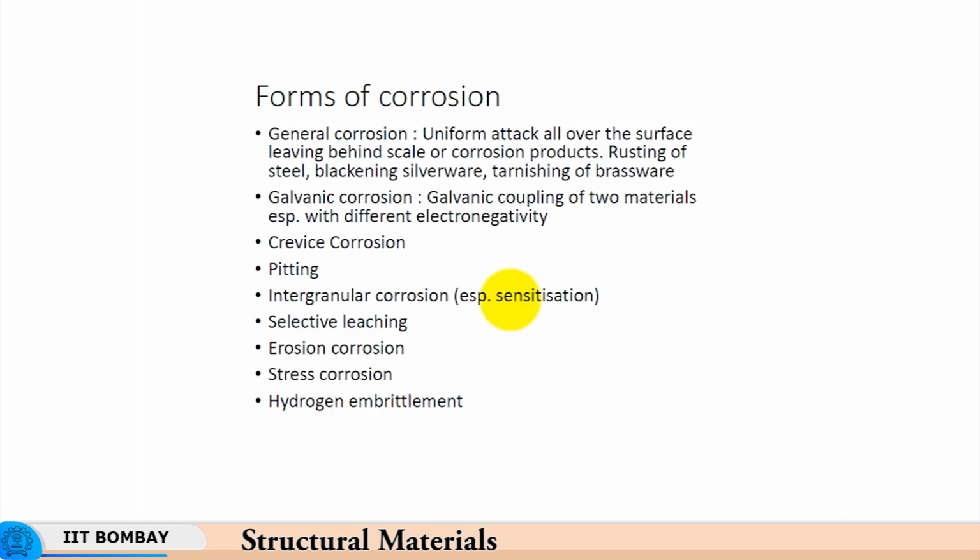So, in a dissolved condition, and this atomic hydrogen is able to diffuse very rapidly and it goes up the stress gradient, and wherever the stress is maximum, it will result in a brittle failure. So, this is also called delayed cracking, meaning that one does not really realize that the hydrogen has entered the system, and when the hydrogen diffuses to a highly loaded region, there is sudden brittle failure.